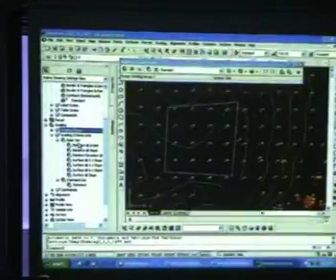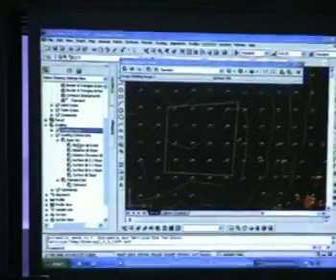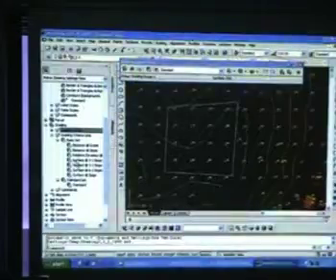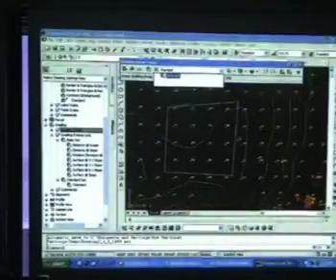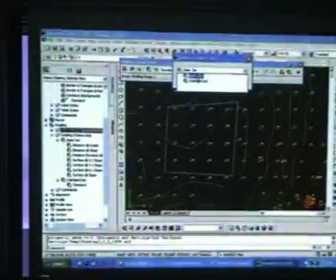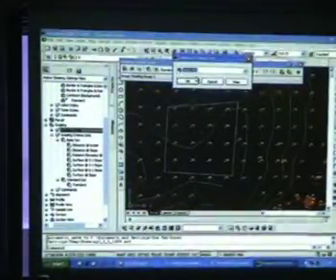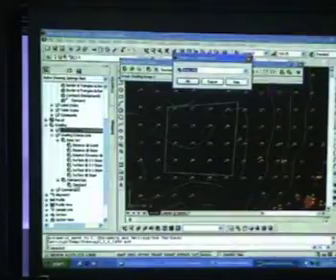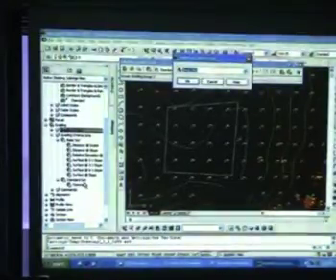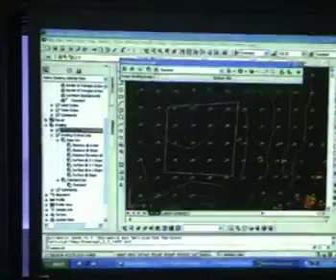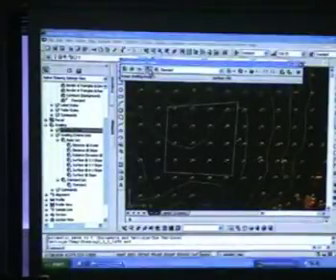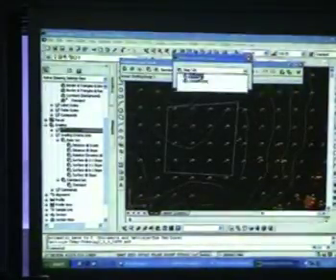For us, if we want it to go all the way up or down until it finds the original ground level, that falls under surface slope. So this is just to show you. I'm going to switch this to basic set, because standard set has only standard, it's got nothing in there. Basic set is the one with the distance at grade, basic set slope. You just click on this icon and switch this to basic set.